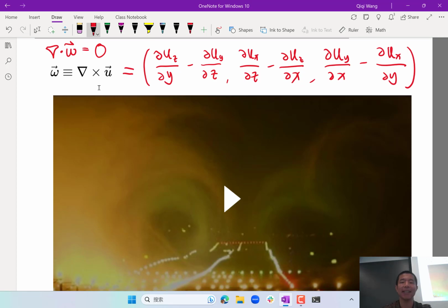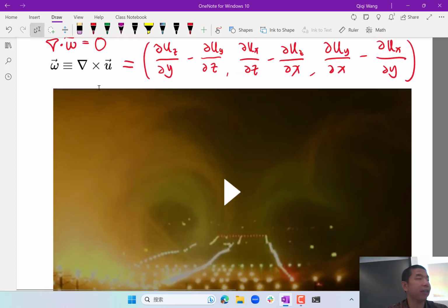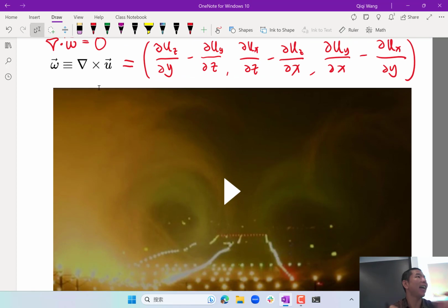If a vortex comes into a point in the flow field and ends there, this is an impossible scenario, because you can draw a control volume around the end of the vortex and show that the total influx of vorticity into that control volume has to be non-zero.